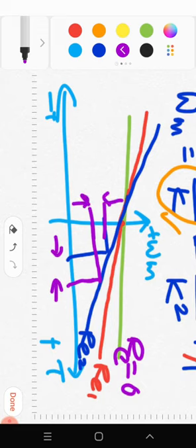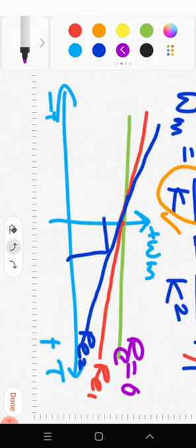So this has become more unstable. Naturally the characteristic is almost flat, so the speed is not getting much affected by change in the torque, whereas now it has become more sensitive to the changes in the torque. So that is one effect of inserting resistance externally to the motor circuit.